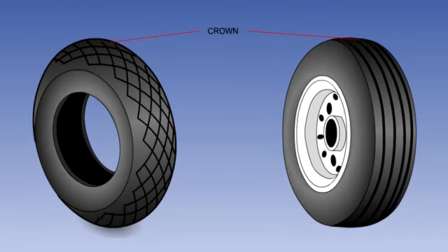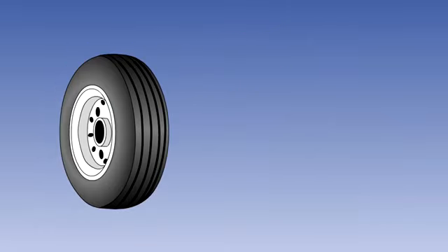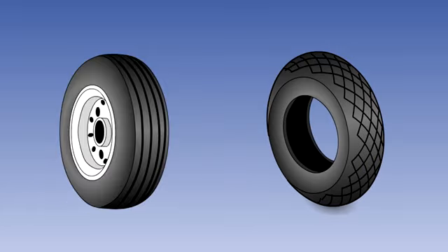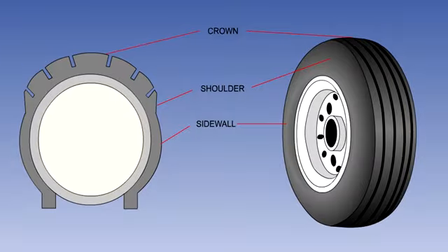The tyre is divided into regions or sections, as illustrated here. The tread of the tyre is situated in the crown and shoulder section. It is worth noting that the term tread is applied irrespective of whether the rubber is plain and smooth or moulded on a block pattern. The sidewall allows the tyre to be flexible, and the bead is seated inside the flange of the wheel.